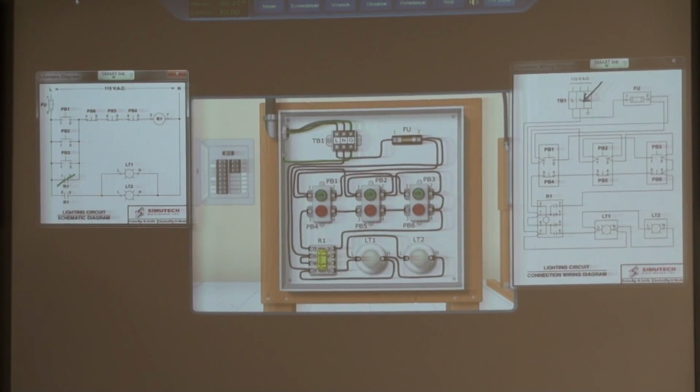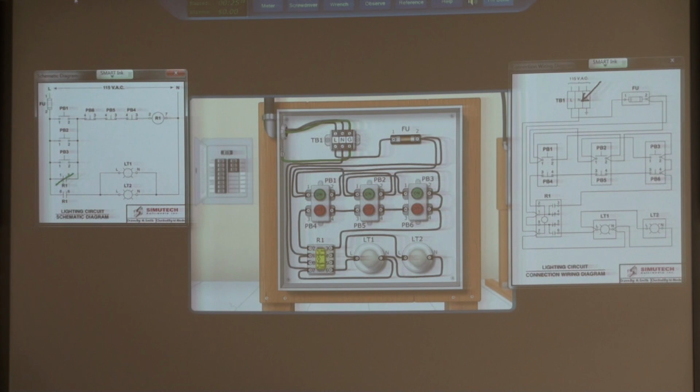We're halfway there. They'll go off as long as you hold down the off button. Yeah, that's what I was thinking. If I press PB6 down, they'll go off. As soon as I let go, that path is provided again, and we're gonna go. What is the condition of my relay coil with this guy welded?